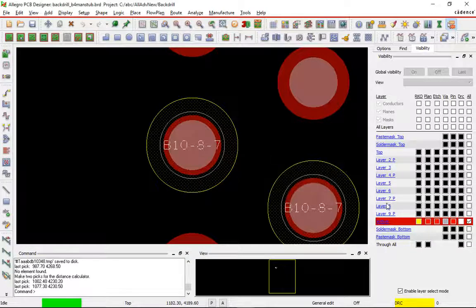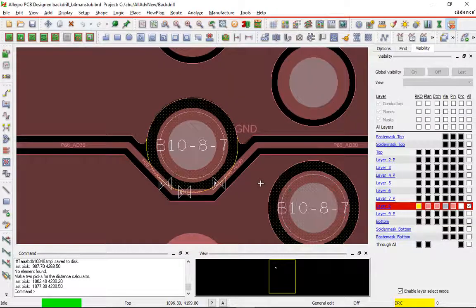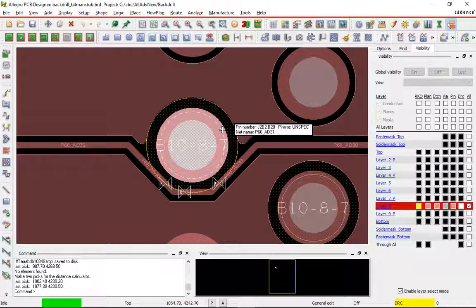Right. Moving on, let's take a look at a routing layer, layer 8. Notice that the added route keep out, which is the yellow again, caused DRC errors with the existing trace. Yet the dynamic shape, which is the shape here, has been automatically updated to void around the keep out. Notice that the regular pad, the pink pad in the middle here, is still displayed even though it's basically back drilled. We could avoid this if you wanted to by using the dynamic pad suppression on.